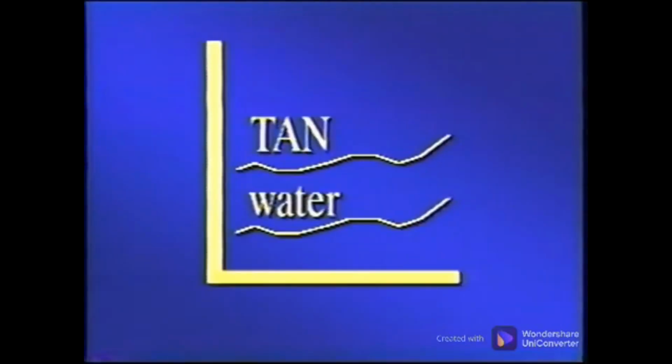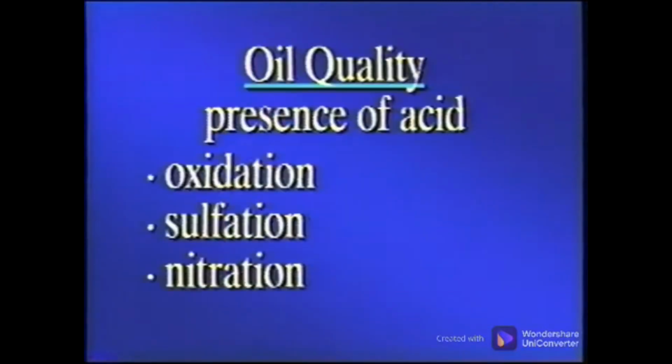Trending these characteristics from the new lubricant condition provides a picture of water contaminants and oil quality by the presence of acid, indicating the oil may be affected by oxidation, sulfation, and nitration. The lab results can be accessed by your computer via modem for instant access, complementing your on-site analysis, enabling you to make the vital decisions about the life of your machine.